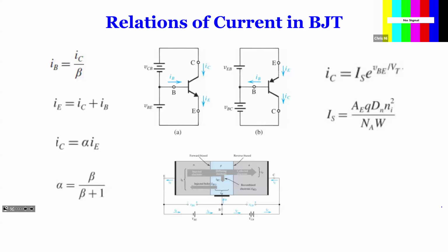You can see clearly for this p-type BJT to conduct, you would have VEB larger than or equal to 0.7. So it's VEB, no longer VBE. In this case it's VBE, but in this case it's VEB. And also, if the transistor is in active or saturation mode, you have VEC as a certain value. But in the n-type BJT, you have VCE either 0.2, 0.3, or whatever that value is if it's in active mode. So that's what you would see.